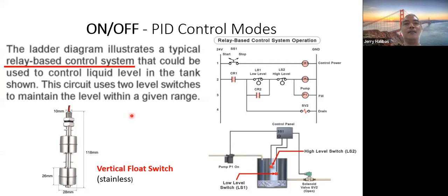So that's why you have to decide. Particularly if you are going to use this on-off control for a water level system in steam condensate recovery, in a dryer system where the condensate returns to the boiler to make steam production more efficient. If you use a microprocessor-based or purely electronic system for the automatic pumping of the condensate back to the boiler, your electronic system will fail, because the environment is hot, particularly near the dryer area, and it quickly suffers wear and tear.